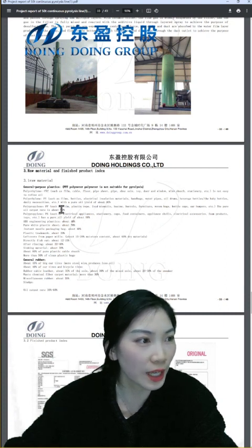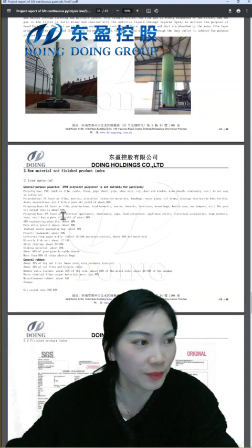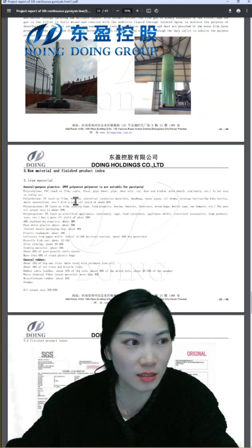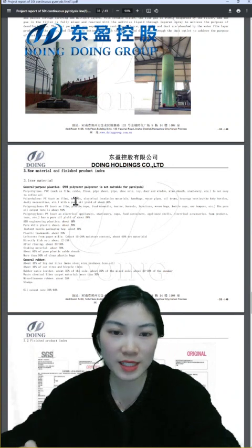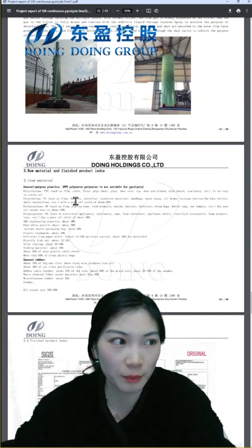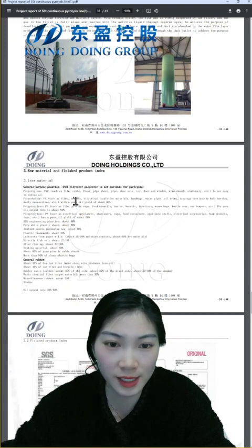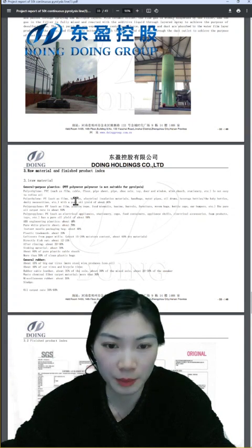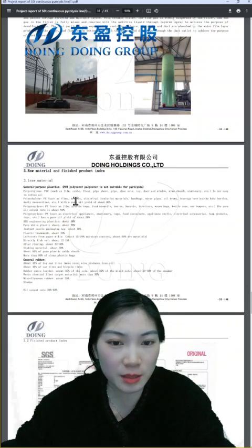And for the plastic, there are different kinds of plastic for your choice. Normally for PP and PE, the plastic oil yield is higher. But for PVC, there's corrosion inside. So normally we don't suggest you use PVC. If there's a little mixed in, that's no problem. But if you mainly do PVC plastic, we will suggest you consider a stainless steel plate. But for PE, we need to note, PE has no oil yield. So normally for the pyrolysis process, we don't suggest you use PE. Except PE, other plastics are all no problem.